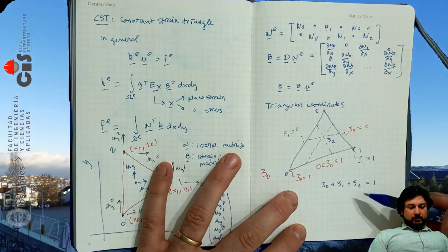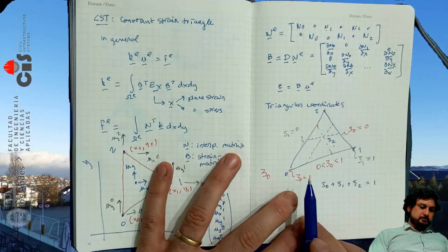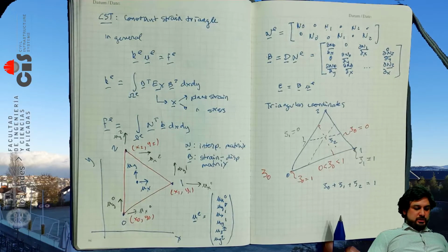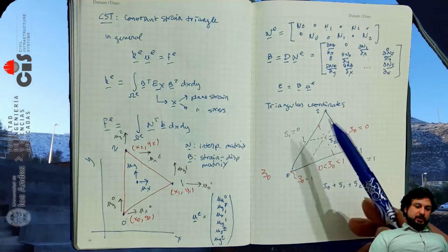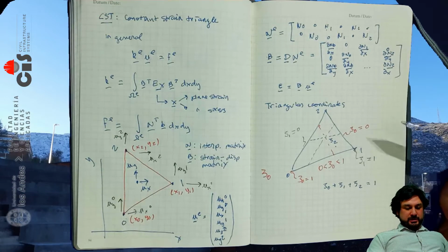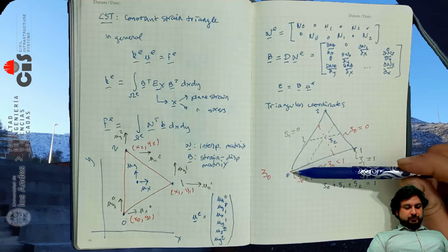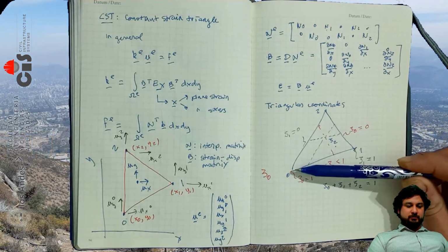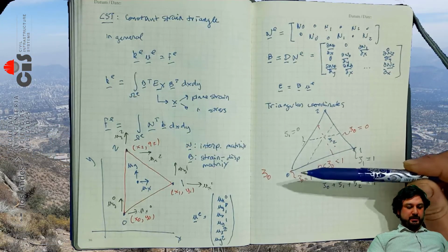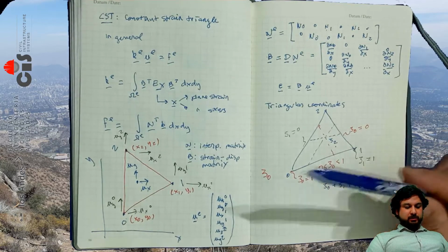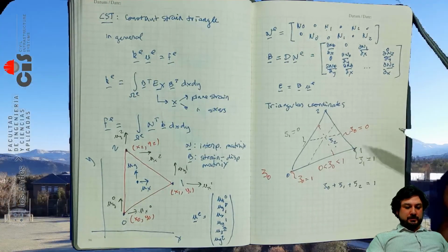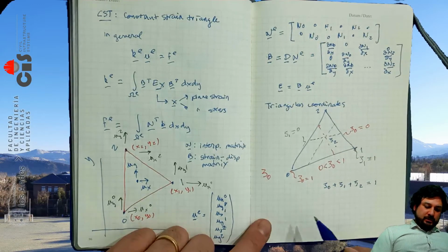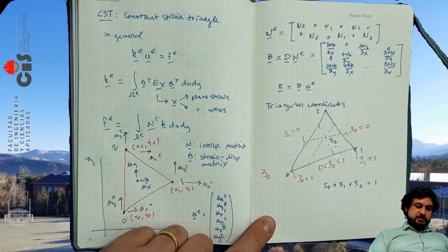Okay, so with that being said, how do you use these to interpolate? Basically what you want is the interpolation to meet the interpolation criterion. If I'm at vertex 0, I want the value of the displacement field there to be equal to the displacement of the DOF, the degree of freedom at that point. The same goes for 1. So this gives us a natural way to do that interpolation, and it is as follows.